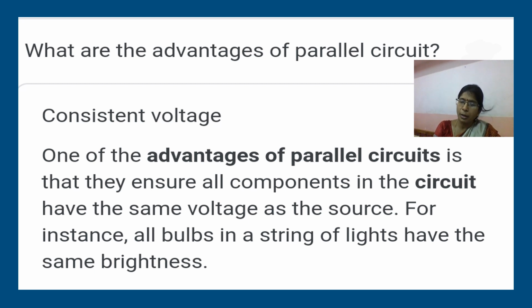Nowadays Christmas lights are available in two types of circuits, that is, in series as well as in parallel. But how can you differentiate them? The circuits connected in parallel have a thread-based base at the bottom of the bulb, like the C9 and C7 types.